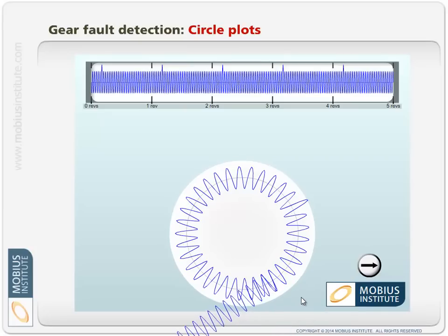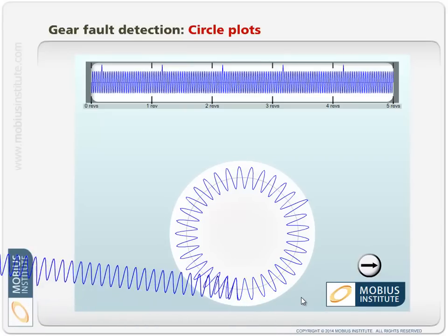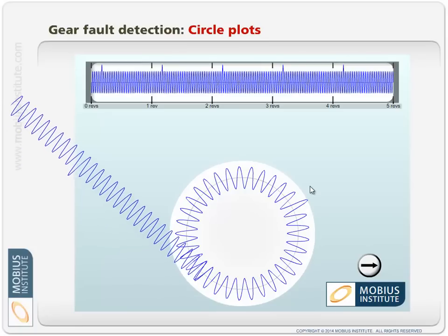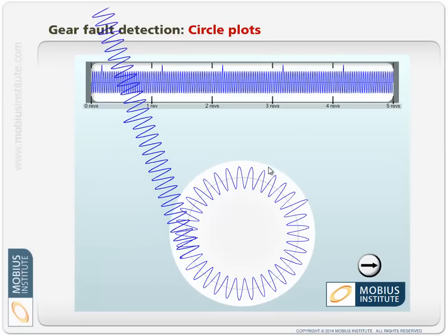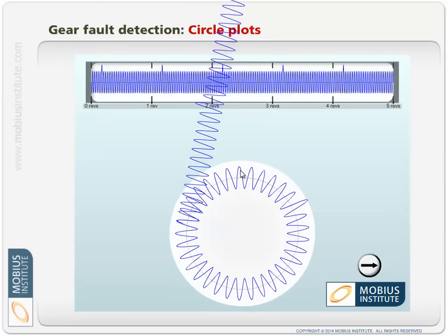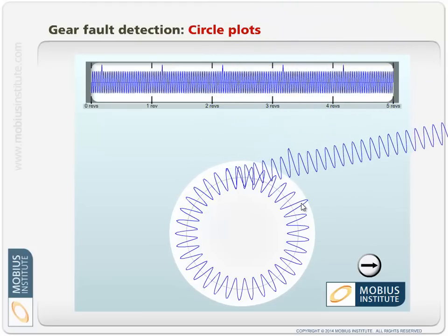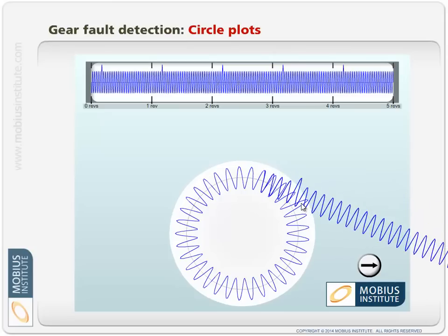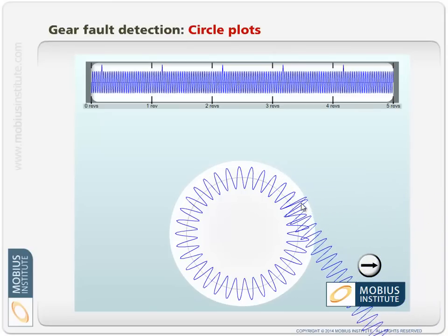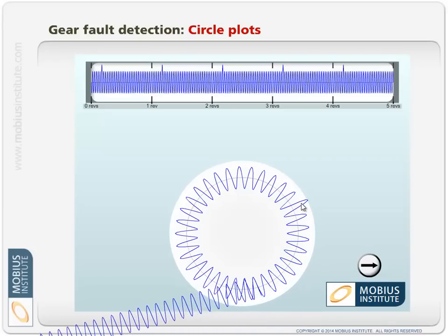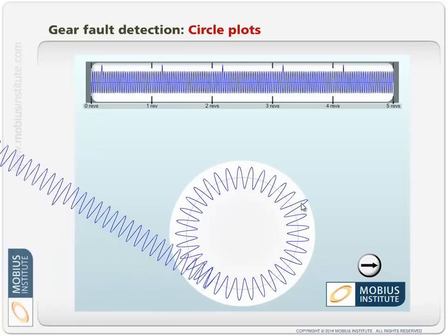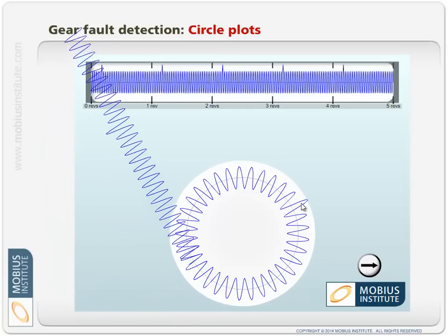And with time synchronous averaging, hey, you can even figure out where they are, because you know that this is the start of the tach signal, and you can say, well, okay, 1, 2, 3, 4, 5, 6, 7 teeth around from where the tach reference was is where the damaged tooth is. Now that'll really freak out any of the guys working on the gearbox when you can say, yeah, not only do I know that there's a damaged tooth, I can tell you which one it is. Man, they're going to be impressed. But anyway,